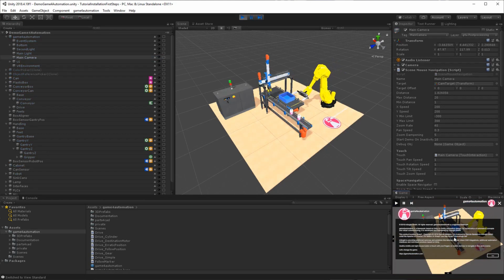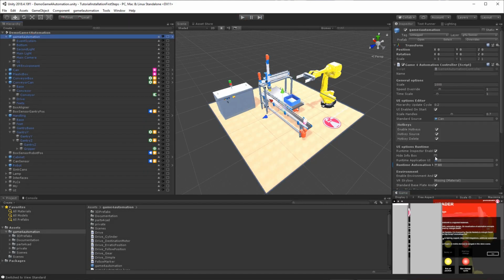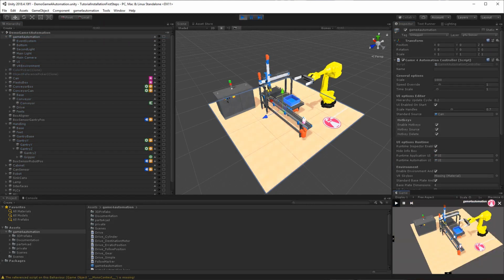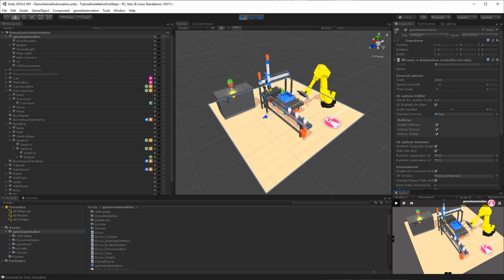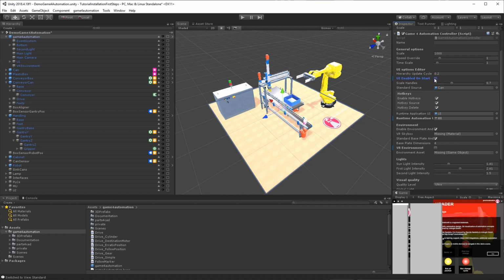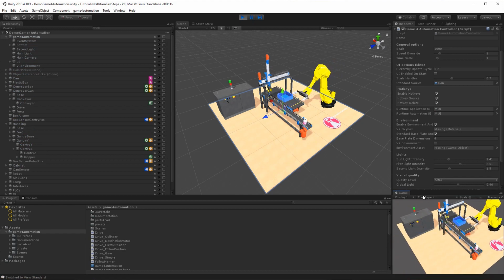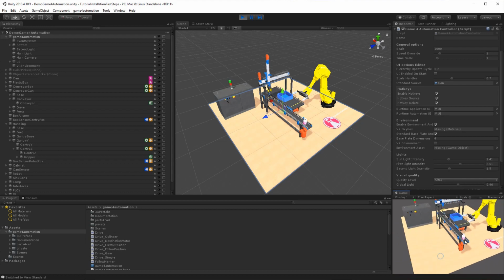that an info box is popping up, and you can stop this info box from popping up if you select here hide info box. You're pushing on play again, and you will see that the scene is directly starting without the info box. If you want to get rid of all the UI components included, you can also select UI, deselect UI enabled on start, and you will have an empty scene without any kind of menu bar or runtime inspector components included.